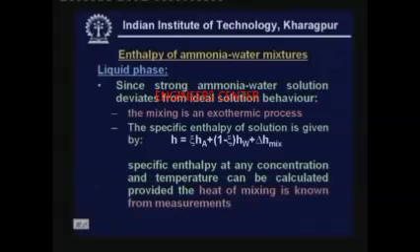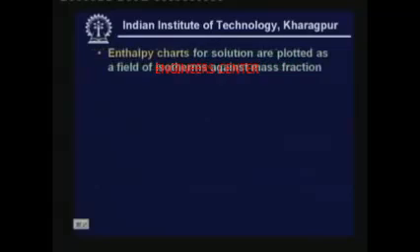And the specific enthalpy at any concentration and temperature can be calculated from the above expression, provided we know the heat of mixing. Heat of mixing is normally obtained from measurements. Now, enthalpy charts for solution are plotted as a field of isotherms against mass fraction. In fact, I will show you the typical enthalpy chart for ammonia water mixture in the next class.